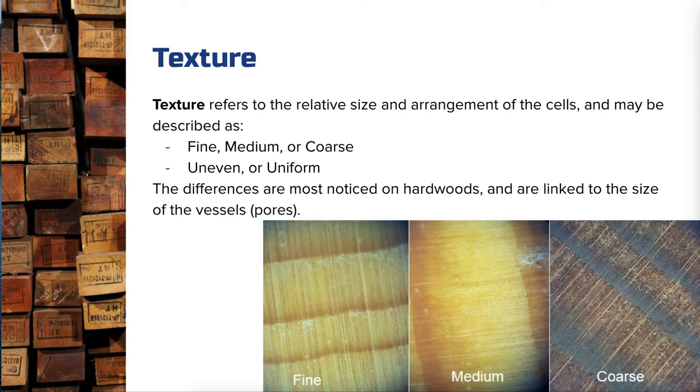So I know, for example, that if I was making a chopping board, I wouldn't want it to absorb a whole heap of meat juices and vegetable juices and things like that while I'm cooking. So I would not want pores. However, for the purpose of keeping my knife sharp, we actually want to use end grain typically, which increases pores. So it's not always a direct link between smoothness and sealing and the texture, because there are other ways that we can go about filling those pores to render them food safe.